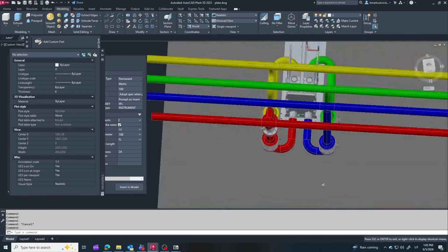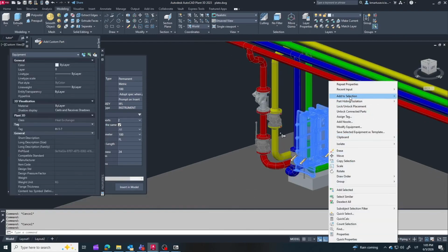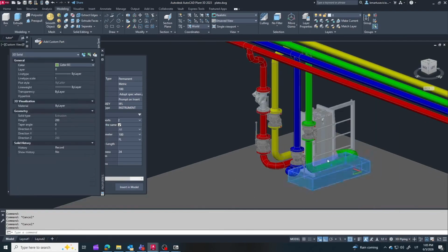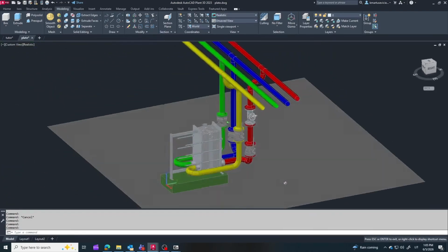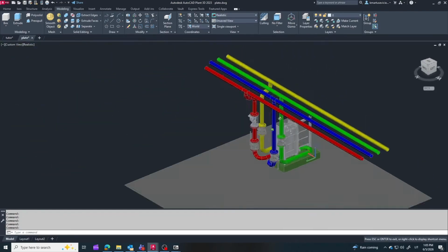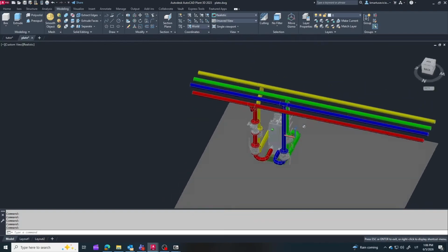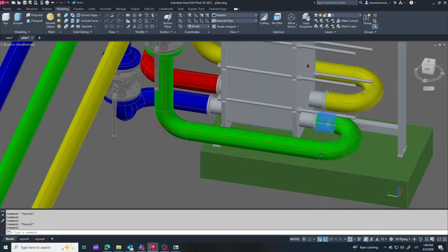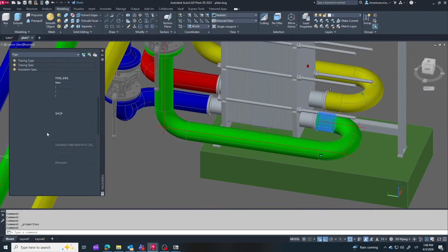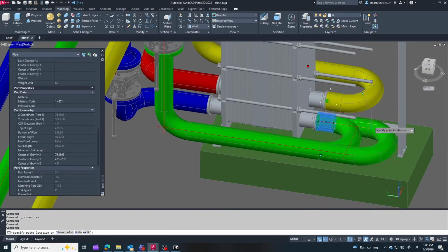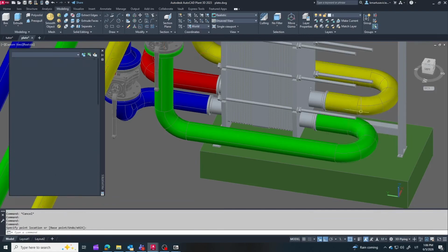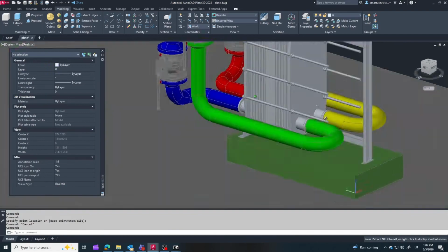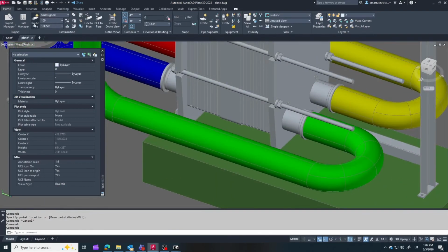Now let's talk about two small but absolutely critical details that separate amateur models from professional, high-end plant design: high point vents and low point drains. Now, at the absolute lowest point of the system, I'm preparing a 200 millimeter straight pipe run for the drainage branch. This length gives us a solid, clean drop to clear any surrounding insulation and ensures the drain valve is easily accessible. For this drainage branch, a DN25 line is going to be absolutely perfect.